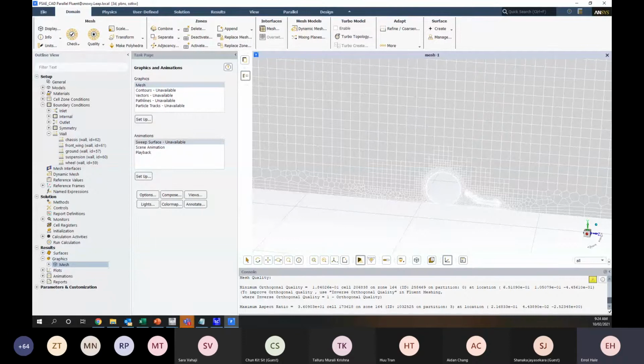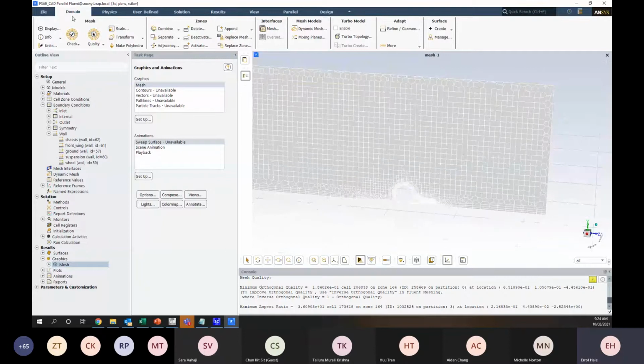Would polyhex core be appropriate in supersonic cases where shocks will penetrate into the bulk flow field? That's a difficult one. Sometimes with supersonic cases, it can be really important to have your mesh elements aligned with your shocks. So in that case, no. Generally, you might want a tetrahedral grid or some kind of structured grid where you can have partitions in your grid that are basically at the same point as the shocks are expected to be. So polyhex core would not always be great for supersonic cases.